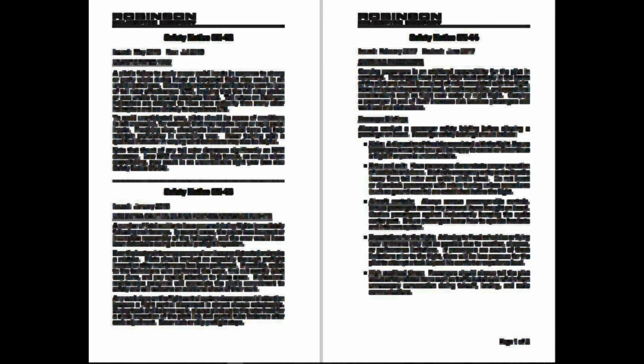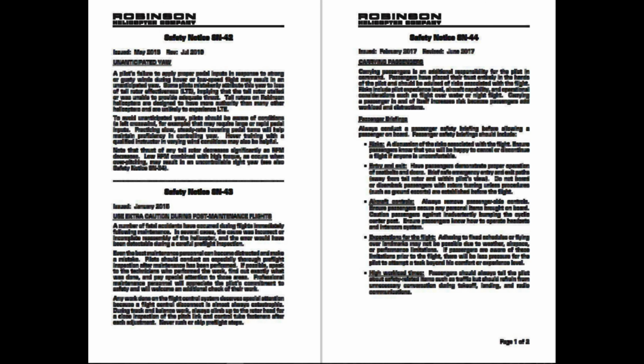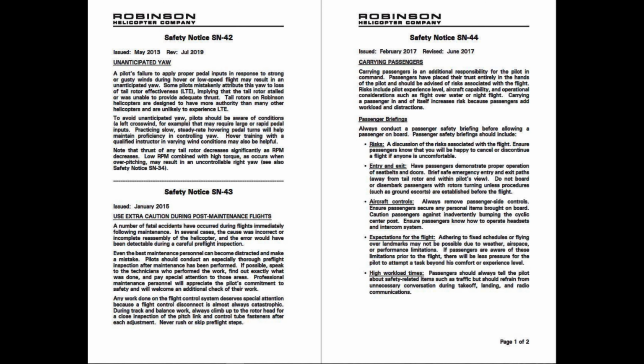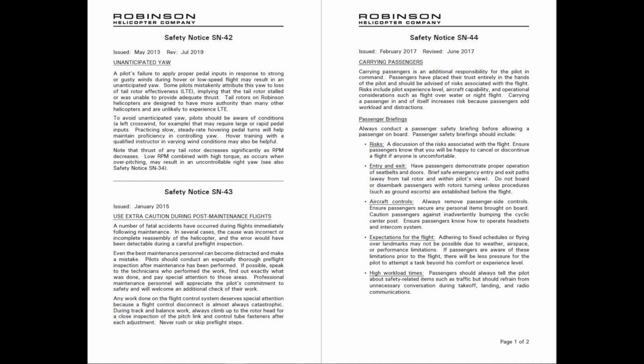While doing the pre-flight inspection, the pilot reads the journey log and notices that the aircraft just came out of maintenance. Once noticing this, should the pilot do anything differently? Yes, the pilot should do a more thorough pre-flight inspection just in case any of the parts were not assembled correctly or thoroughly. Sometimes a tool might be left behind as well. If it's not written in the journey log, the pilot should talk to the maintenance personnel and find out what specifically was done so that they can give a more detailed inspection to those areas. This is especially the case with flight control systems.